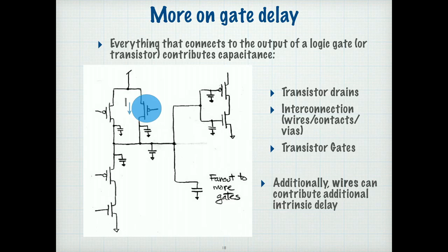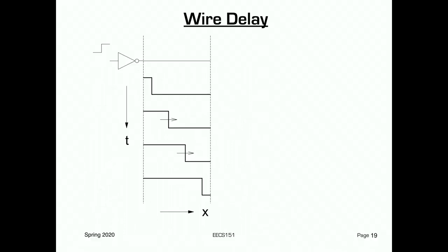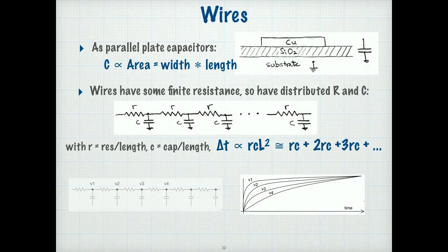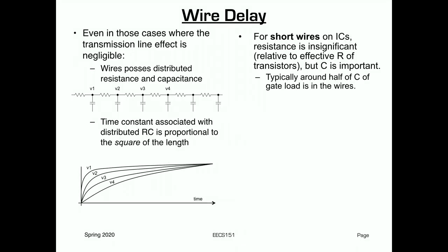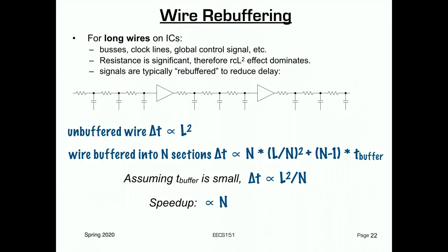Right? You can think of it as little local capacitors, local places to store charge. So when the transistor turns on and tries to draw some current from the power supply, it can drain its local capacitance first. So it doesn't have to put as much of a demand on the wires that are leading to the logic gates. Right? It tends to make all the signals smoother and less noisy. We'll see more about that later. Okay, so that was wires for now. We're going to visit wires again in a little while.